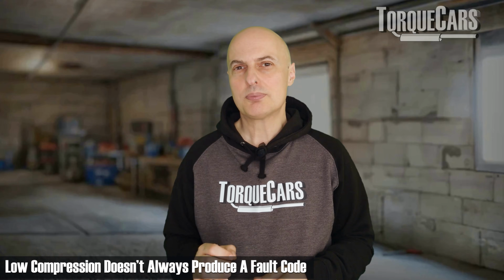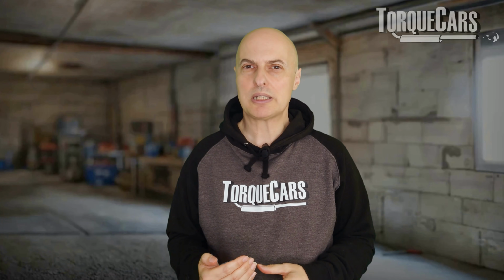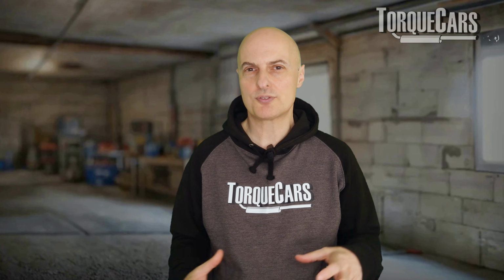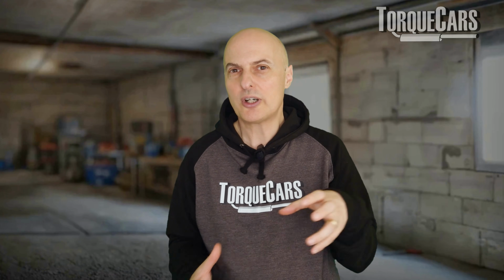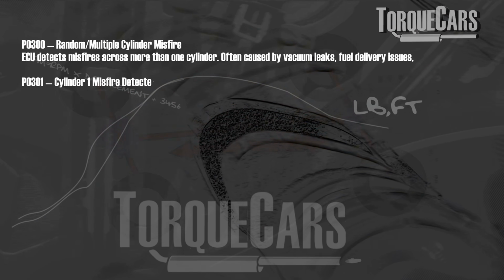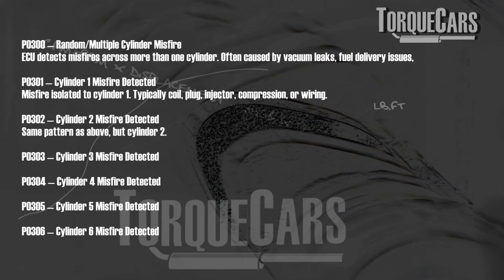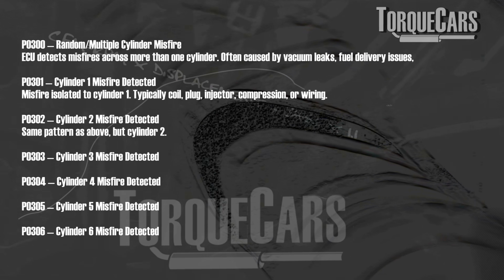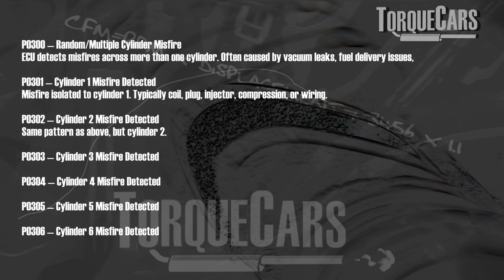of the problem. Low compression doesn't always produce a fault code, annoyingly, but you might get codes that relate to persistent misfires from weak compression. If there's not enough compressed air, it's not going to fire correctly, it's not going to burn correctly. So you might see a P0300, a P0301 or a P0308 error code. The P0300 part indicates it's a misfire, and the subsequent codes will give you a clue as to which cylinder